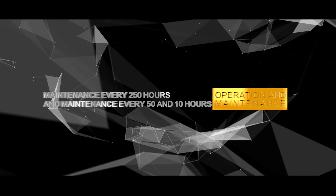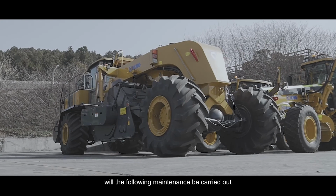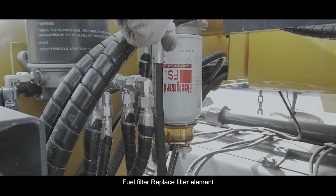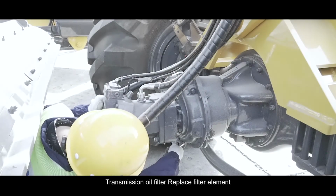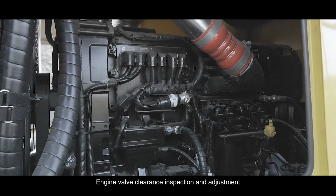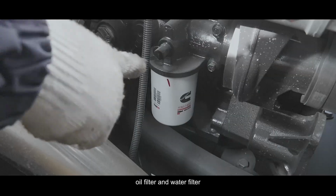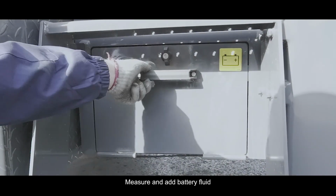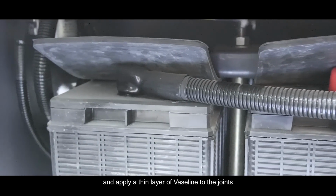Maintenance every 250 hours, together with maintenance every 50 and 10 hours. Only after the first 250 hours of operation will the following maintenance be carried out. Fuel filter, replace filter element. Transmission oil filter, replace filter element. Engine valve clearance inspection and adjustment. Replace the 3 engine filters, namely diesel filter, oil filter, and water filter. Measure and add battery fluid. Clean the surface and apply a thin layer of Vaseline to the joints.